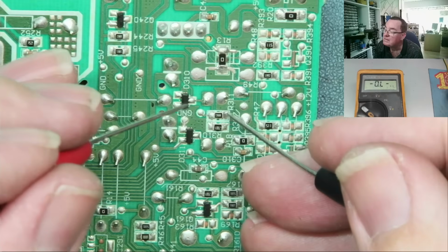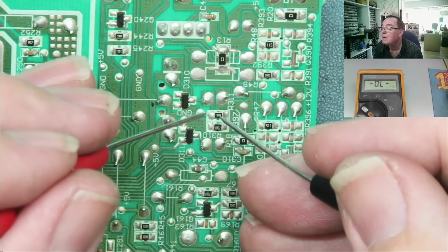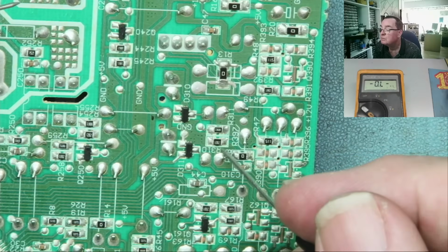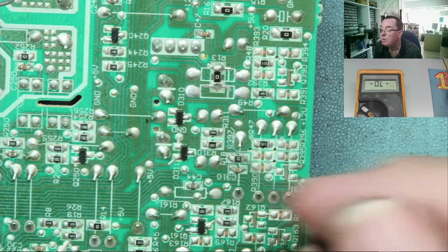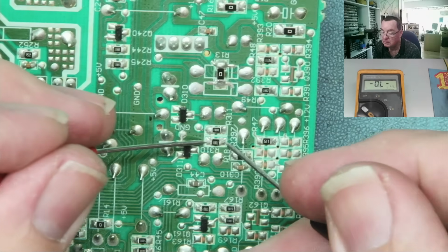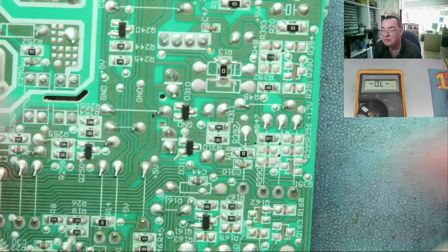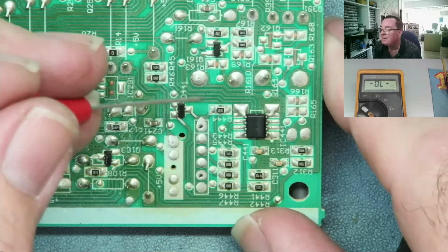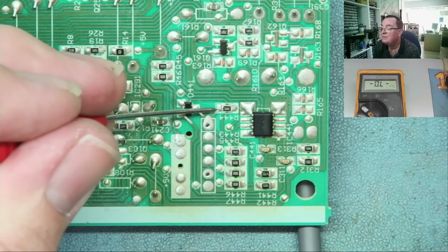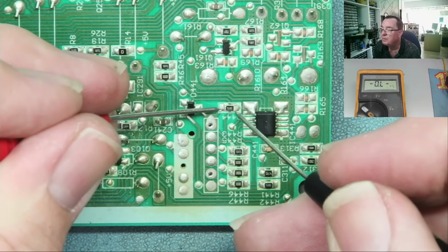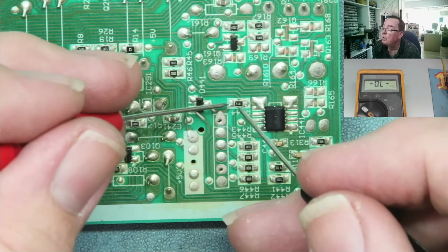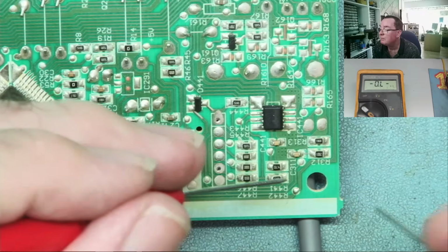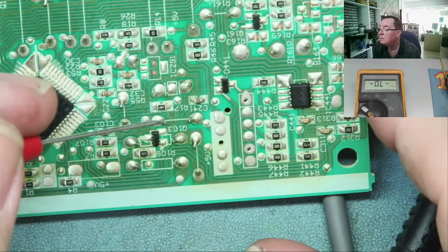The value of these are fairly easy to read, by the way. So like 8061 is 8.06k. This will be a very close tolerance resistor. 2001, 200 and one more 0, 2000, 2k. Yeah, which it reads basically. Very close, okay. So if you want, you can test them all, but generally if these things fail, apart from very high value resistors, they tend to just burn up. 5101, so 510 and one more 0, 5.1k. Yeah, so you can go around these things and test as many as you feel like.